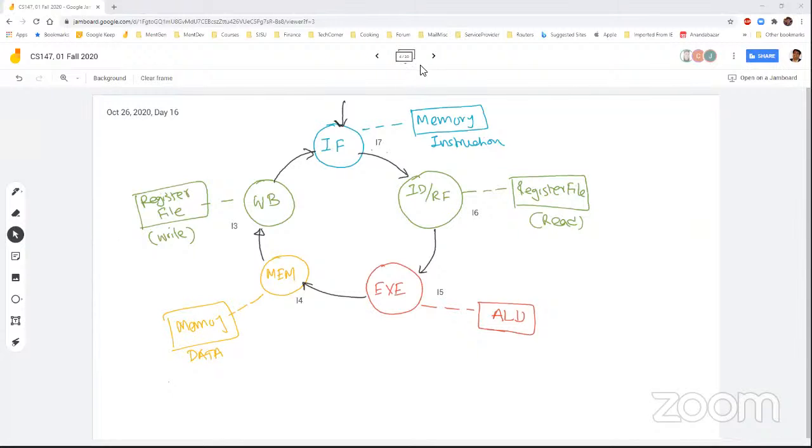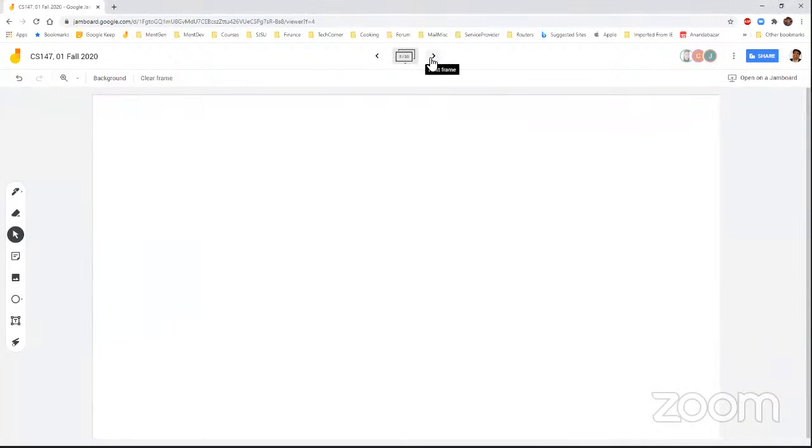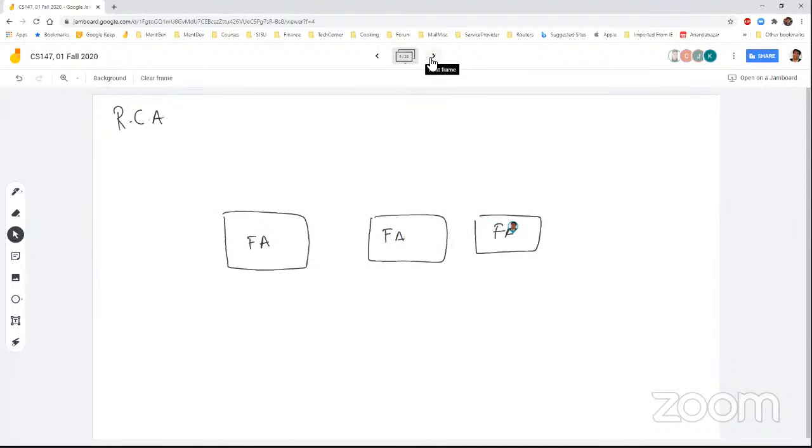If you go back to your adder circuit, your ripple carry adder, remember it has daisy-chained full adders, let's say 4-bit: full adder 0, full adder 1, 2, and 3. And your summation is being computed in the LSB to MSB direction, right? Gradually.